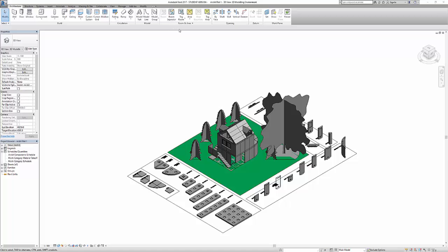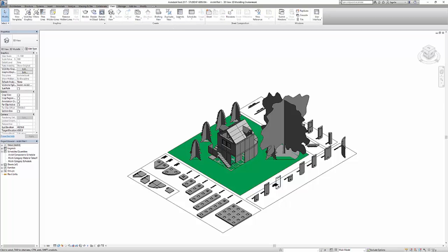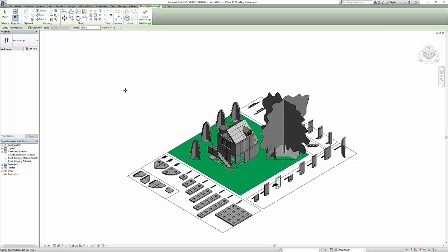To create a walkthrough, select on the View tab the option on the drop down under 3D View Walkthrough. You'll instantly be taken through to a new drawing option, and you have a cross-haired cursor. The best way to create a walkthrough is to actually approach your build from a distance away rather than designing your walkthrough up close, because most of your view will be focused on the building rather than navigating around the outside of the building. Let's see how to create one.